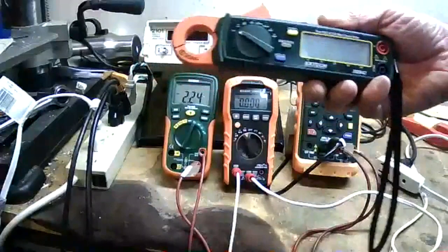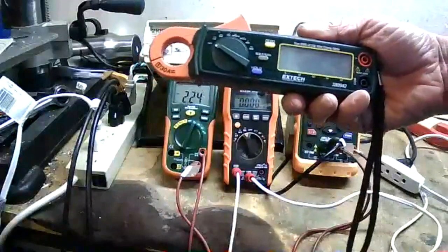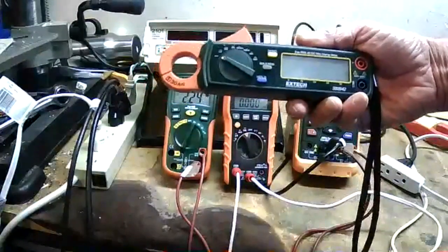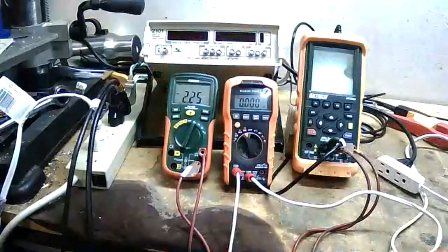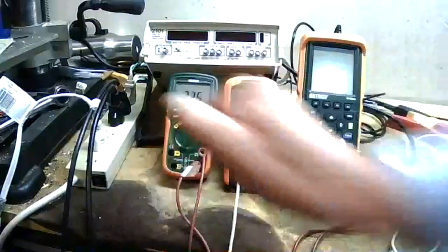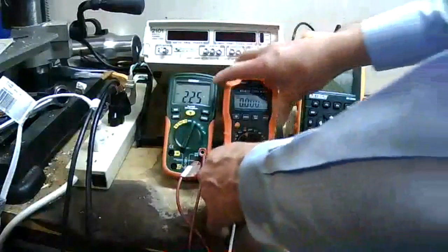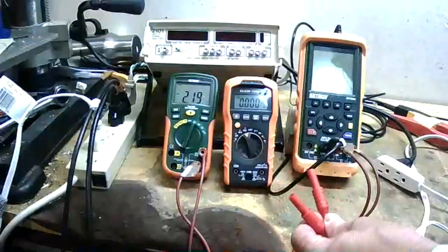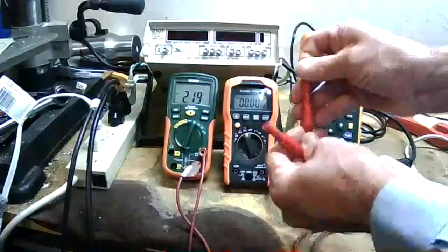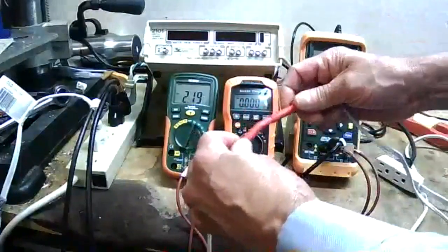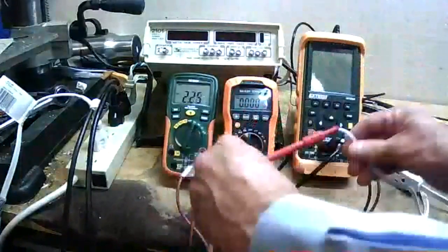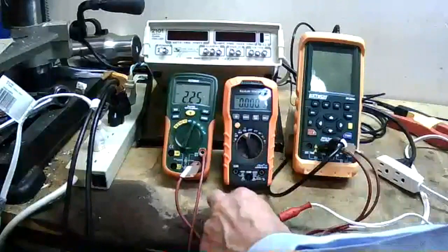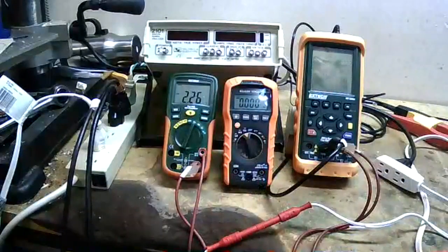How do you do that? I'm going to remove the ammeter from the circuit because we're not going to use that anymore, and I'm not planning to use ammeters anymore in this class. So power is off. Shrouded connectors. I'm protected. I'm just going to connect the energized part of the circuit together. So now I have a closed circuit. Nothing measuring the current.